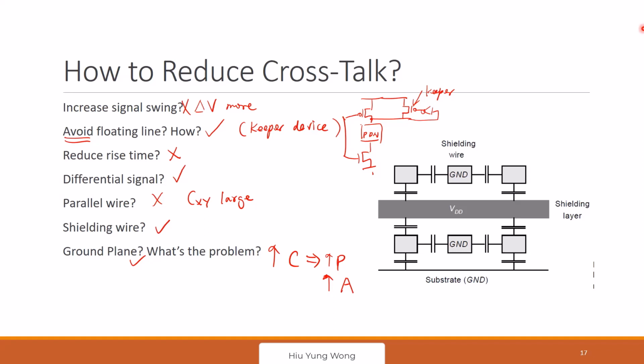So you mean you have an analog system and also a digital system, right? You want to separate them as much as possible because the digital system has a lot of noise and the analog system doesn't like the noise, right? So you want to separate them. And your clock should not run over the analog because they don't need the clock. Try to avoid that.